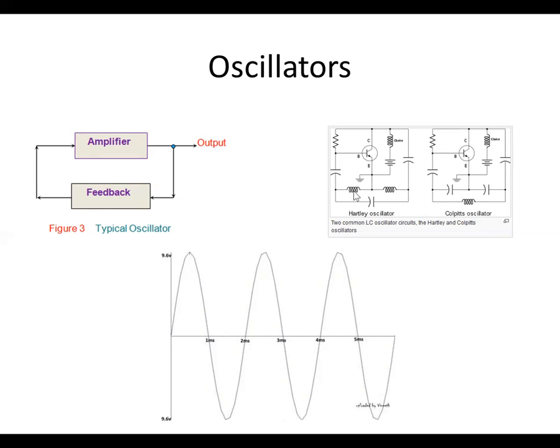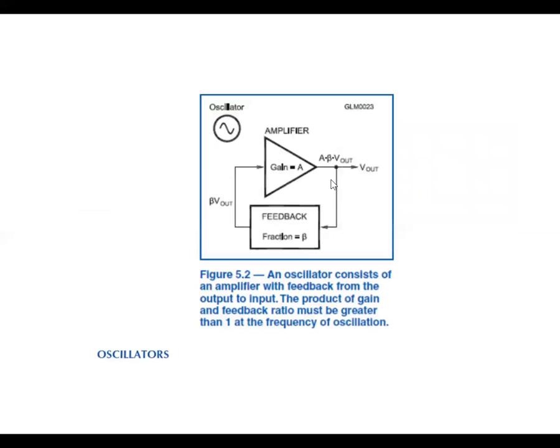Over time, the oscillator would just get slower or lower in magnitude if you weren't replenishing the system energy with either the transistor or an operational amplifier. So you always need an amplifier of some sort in an oscillator.